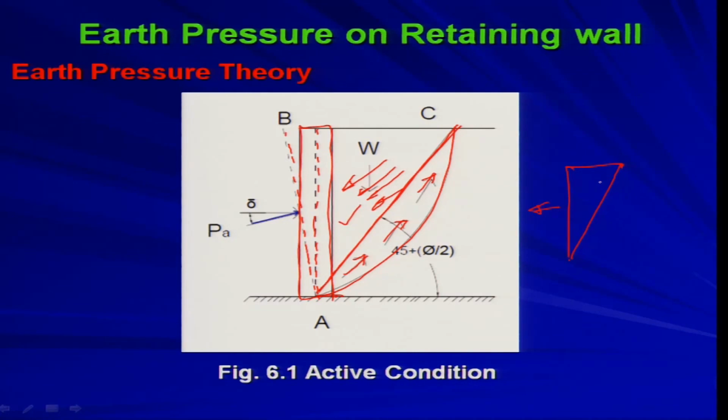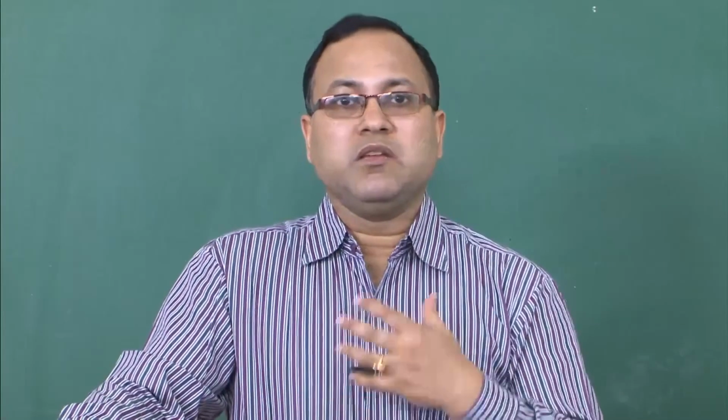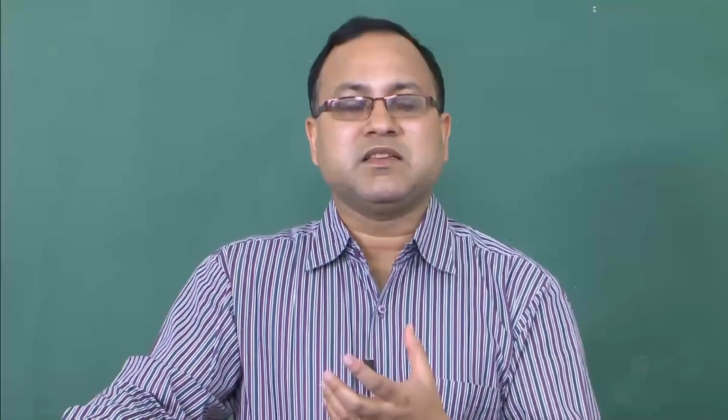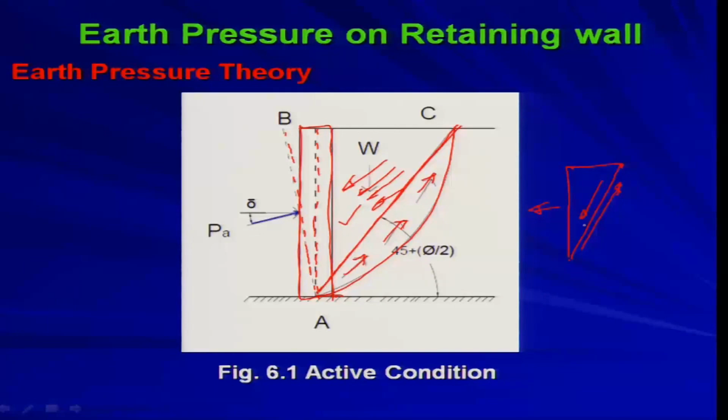So this is the direction of movement, and you get the resistance developed at the failure surface. This resistance is nothing but your shear resistance, as we discussed in the last chapter: every resistance you generally get from the soil is based on shear resistance. This resistance is developed and gradually mobilizes, and when the complete mobilization of the shear strength is done, the wedge will move along with the wall. So, this is the phenomenon.